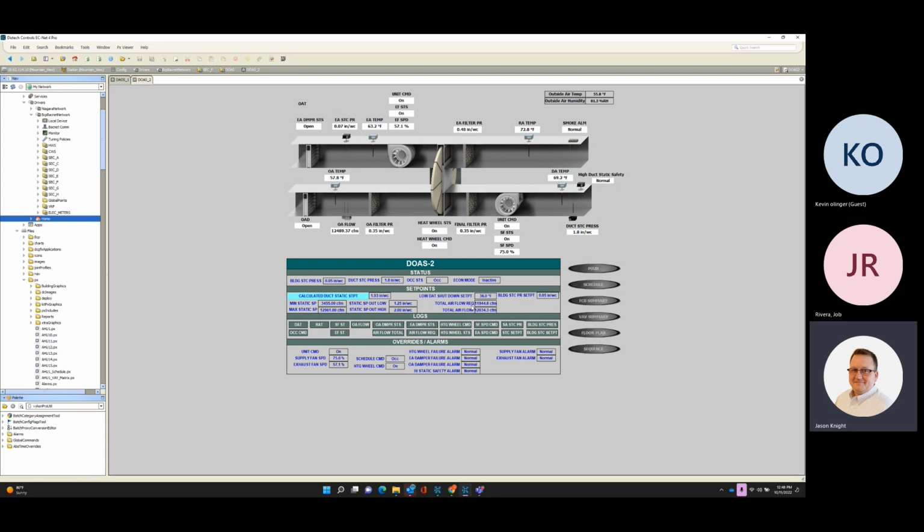So how I did that was I went and queried every 15 seconds. I have a program running that says, hey, what is the effective airflow set point of every box? And then it totalizes it and gives me this number. Then I go back and I look at the actual airflow. So here's the total of what all the boxes are asking for. They're asking for 11,978 CFM, which is almost at our 12,961 CFM set point.